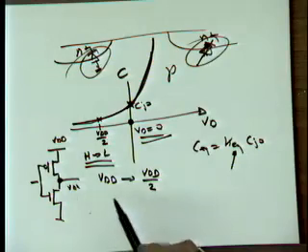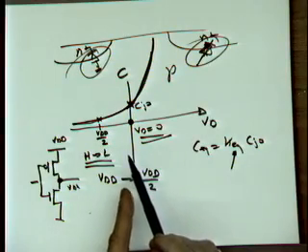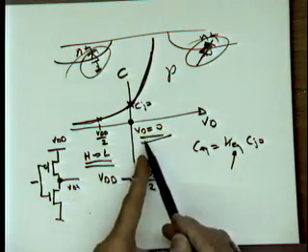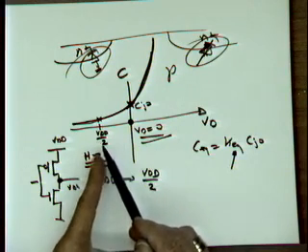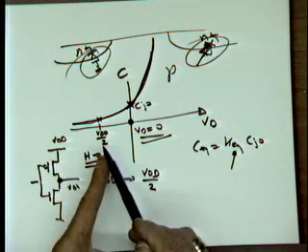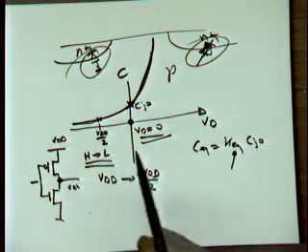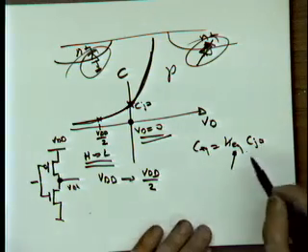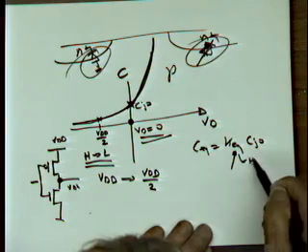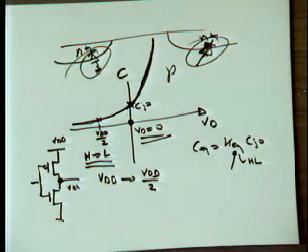For the PMOS device, we're going to start with VDD, with 0 voltage over the diode, and the maximum value in the midpoint is VDD over 2. Okay? And that's the way we compute K equivalent for the PMOS for the high to low transition.